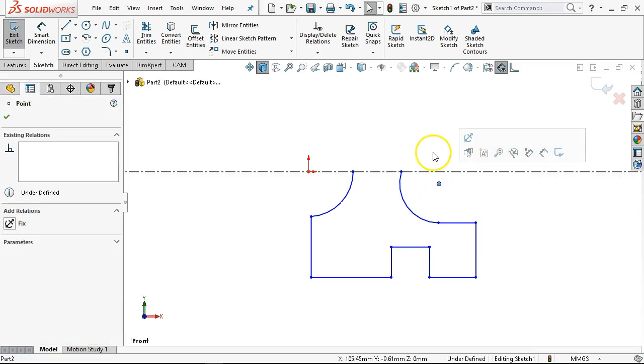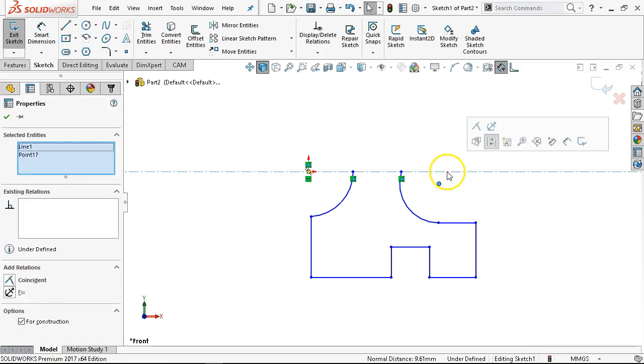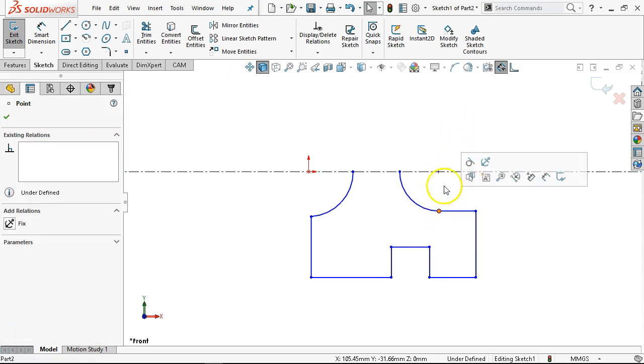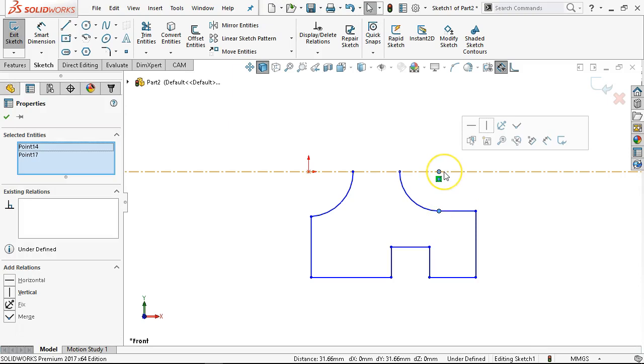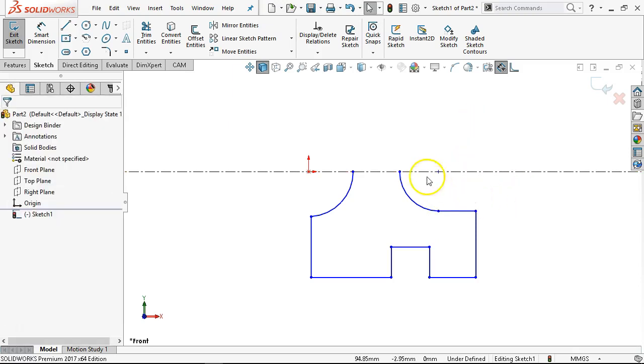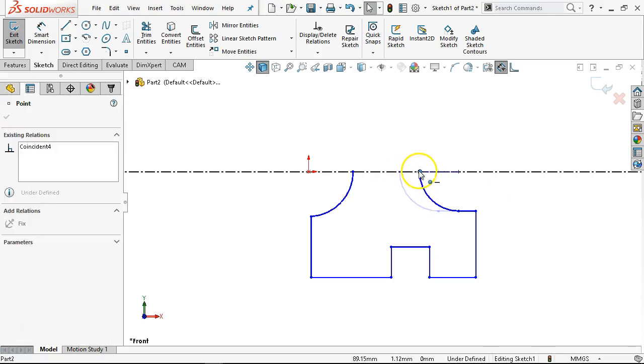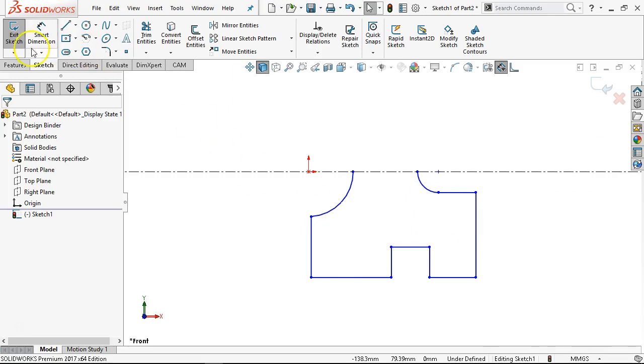and get it to do what I want it to do. All right, so the center point is going to be laying on the center line, so I'll make that coincident. I want those to be a full arc, so that the end point and center point can be vertical. And I'm just laying that out to where it's forcing it to be a 90-degree arc.